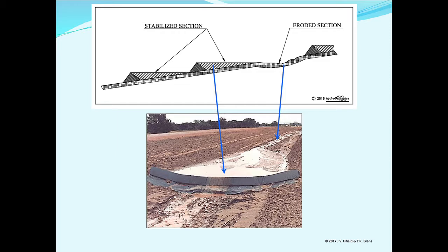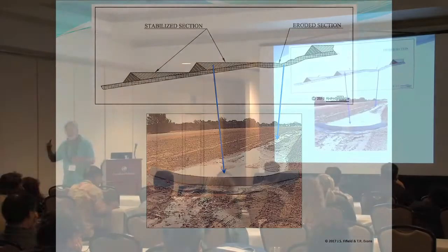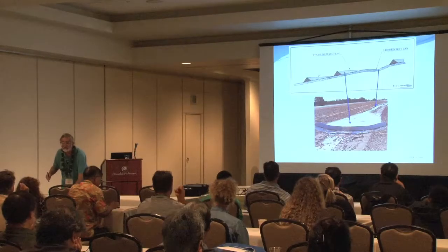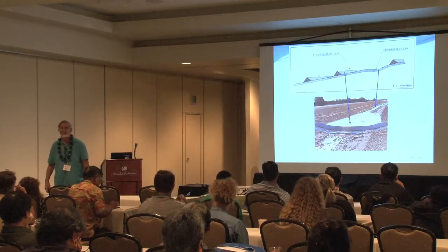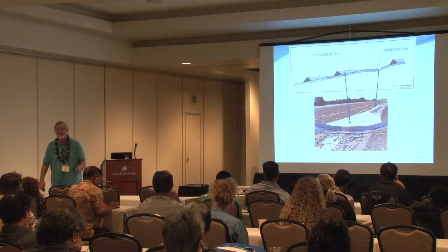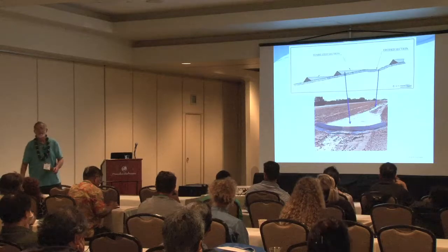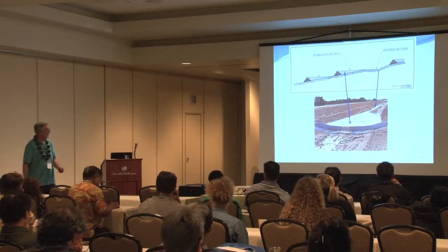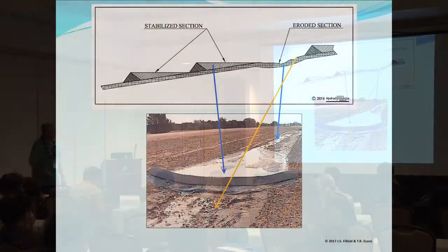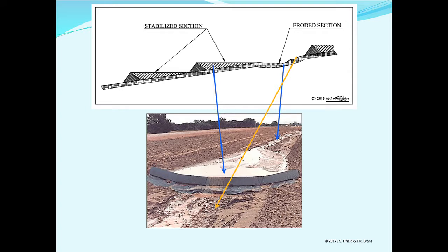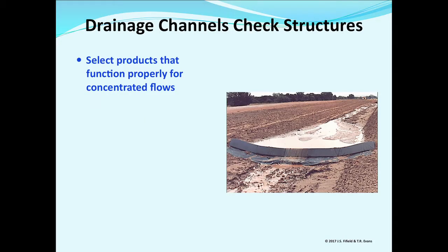Flat land? 15% slope? Did you look at that? No, that's what was in the manual. It says put them every 15 feet apart. We've done it for 25 years that way. Wrong answer. Think about them. Analyze them. See what works. See what doesn't work. Because you'll get some deposition here, but you're going to get a lot of erosion over there, and you got to be very, very careful about how you handle them.